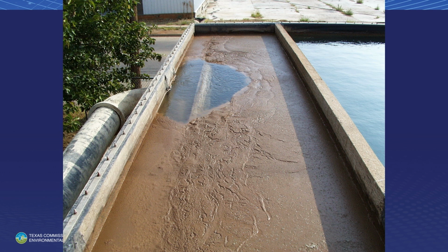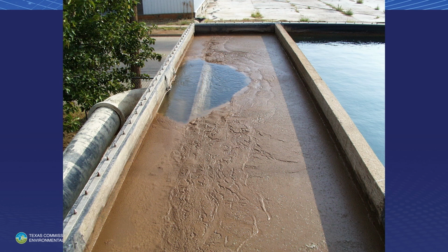And in both those conditions, what we're having is oils from that vegetation, or oils from the rupture of the algae cells as they die off, that are imparted into the water. Well, you take an oil like that, bring it into the plant and hit it with sodium hydroxide, that's called saponification, which is a fancy term for soap making. When you make soap bubbles and try to flock, that flock gets attached to them, and now you've got a DAF unit, you don't have a sedimentation rate, okay? So it all comes to the surface and you have that situation going over into your clarifiers.